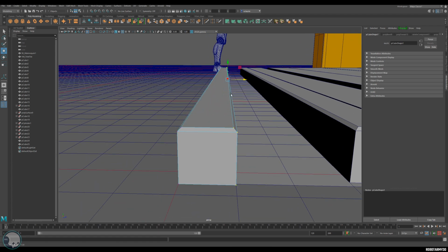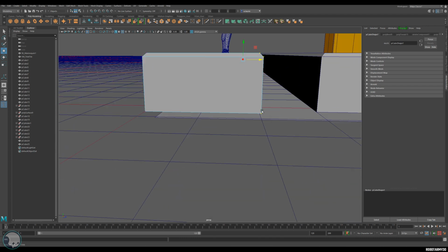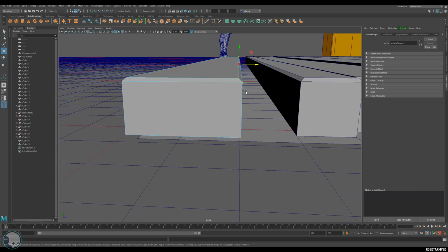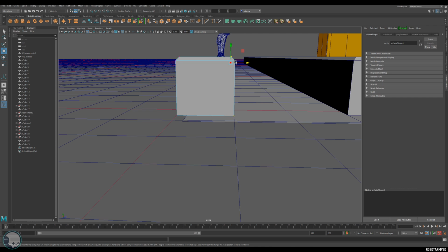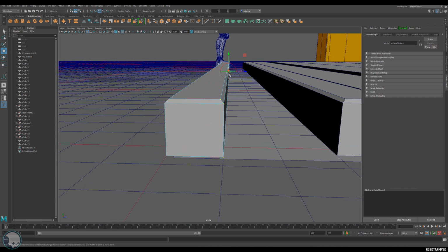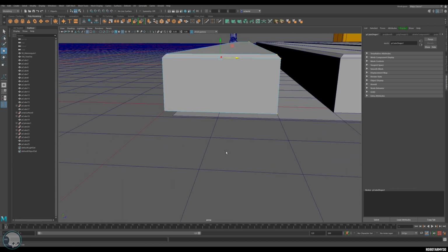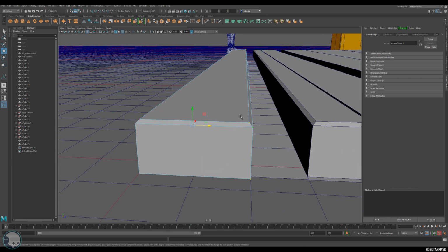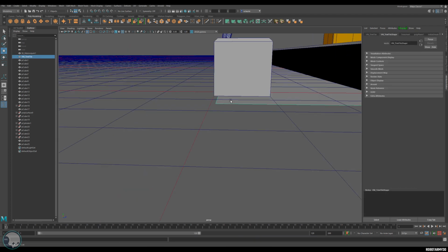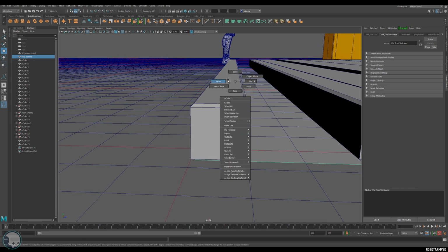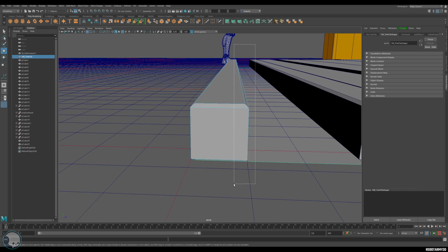So if you're moving something with a bevel and you've grabbed all these polys, all these vertexes, if you then try to move that, say snap that to a grid, you will find that it'll move it too far because it's going to take the center point of all your selection. So then you need to just move this pivot to the piece, an outer piece, and then snap it, and that way you'll get a nice snap. So just remember that selection sets won't have the pivot exactly where you want them. But for this I actually want to go in, and there's no grid left anyway, so I'm just going to eyeball this. So it doesn't need to be absolutely perfect.